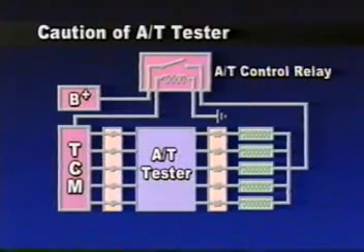While the auto tester is operating, shifting shock happens whenever the gear is shifted because it is not controlled electronically by the TCM. Since the solenoid valve connector is open, the fail code is memorized. Therefore, fault code should be detected by using the diagnosis equipment.